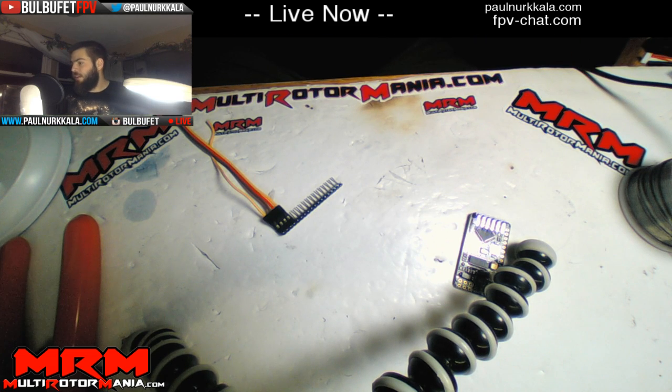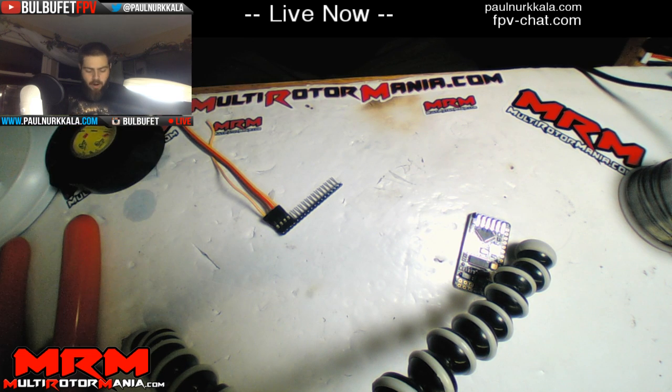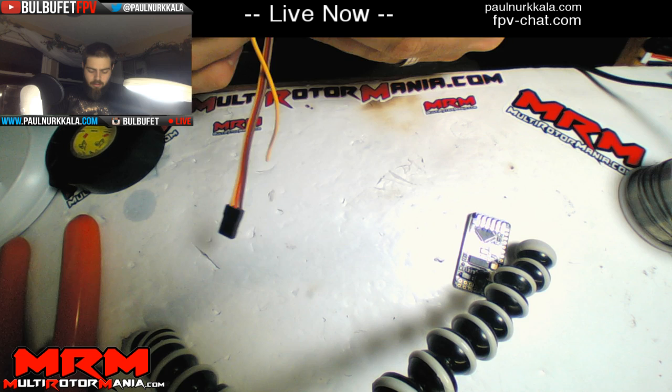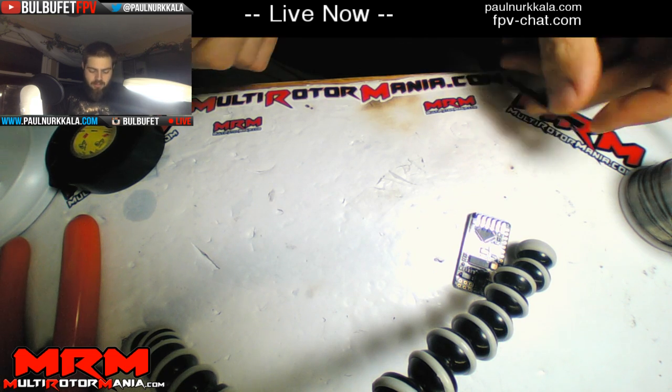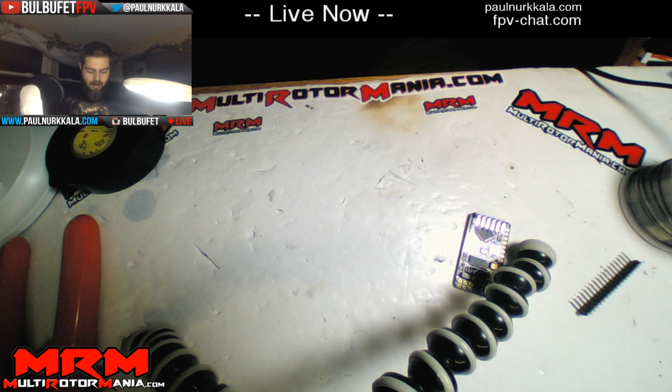Anybody have any questions? Can you make the voltage flash or change colors at a set point to grab my attention? You can configure that. So that's what a chew asks. You can configure when it will flash a big low voltage alarm to the OSD so that you see when you have gotten below a certain threshold.